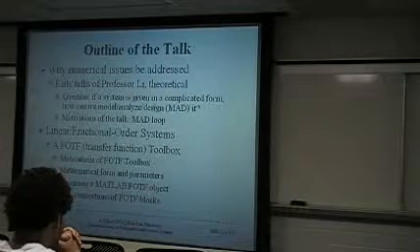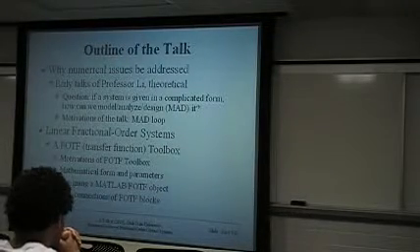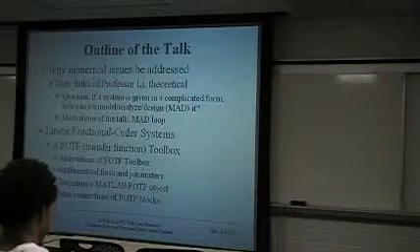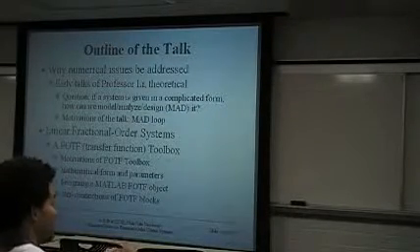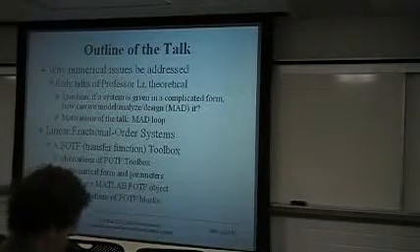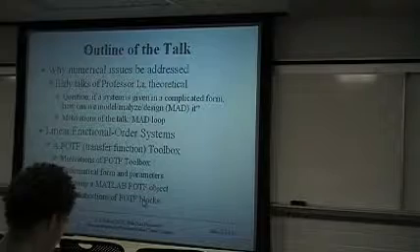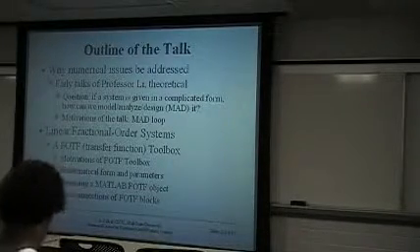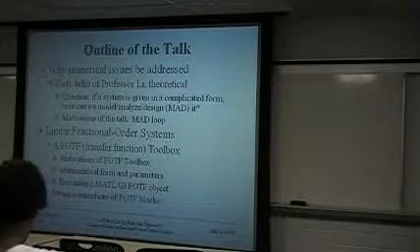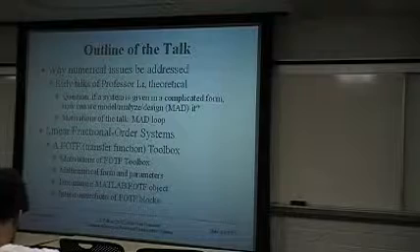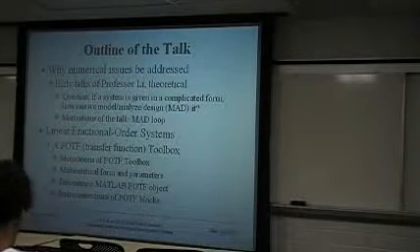As the first part of the Matlab, we will talk about the linear fractional order transfer functions. How can we represent a linear transfer function in Matlab? I designed a toolbox called FOTF, that's for fractional order transfer function. In this toolbox, there is a class or object defined to describe a fractional order transfer function.